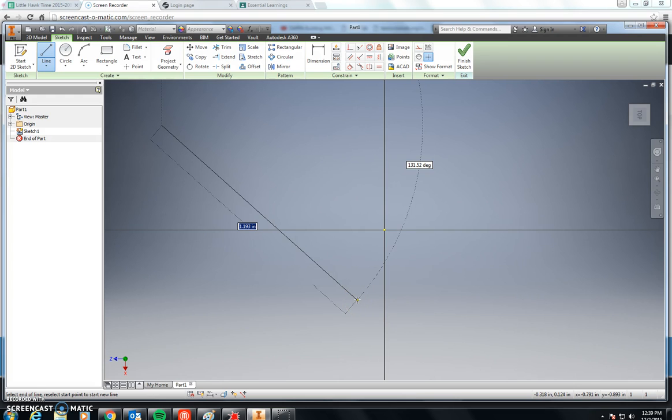Now, in order to make a line a length that you're interested in, you would either pull it, let's say, pull it to the number you want, and then click, and you've made a line that long. Okay. The other thing we could do, and I'm going to hit Escape key and then go back one step. The undo key here is going to be really handy for you. It undoes whatever you've done last. I'm going to click it one time.